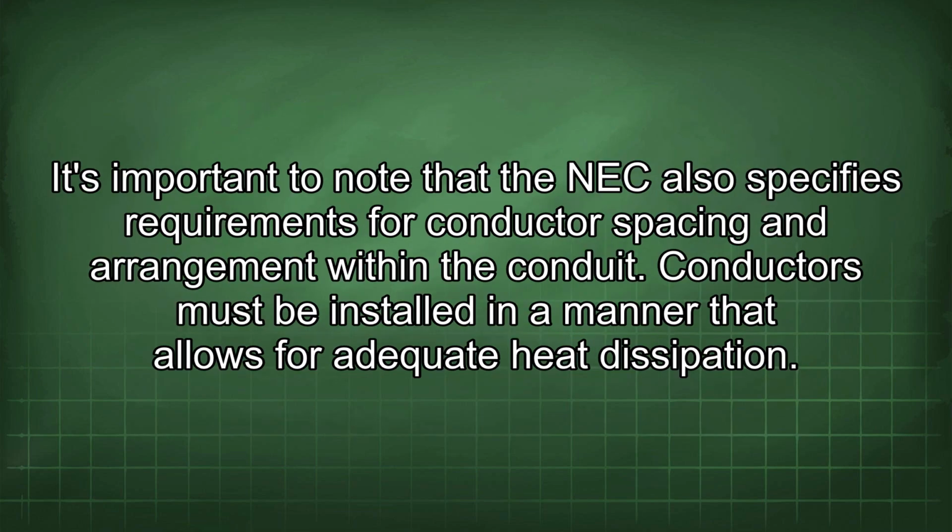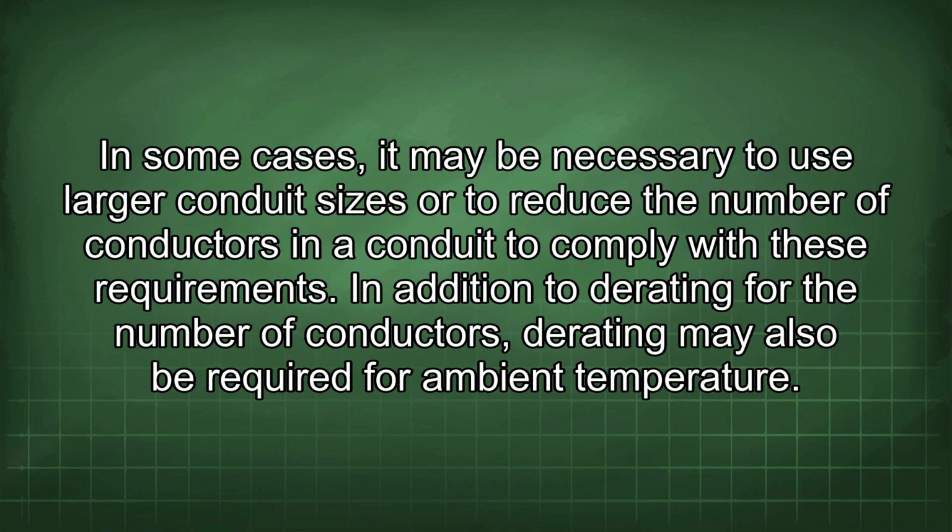It's important to note that the NEC also specifies requirements for conductor spacing and arrangement within the conduit. Conductors must be installed in a manner that allows for adequate heat dissipation. In some cases, it may be necessary to use larger conduit sizes or to reduce the number of conductors in a conduit to comply with these requirements.